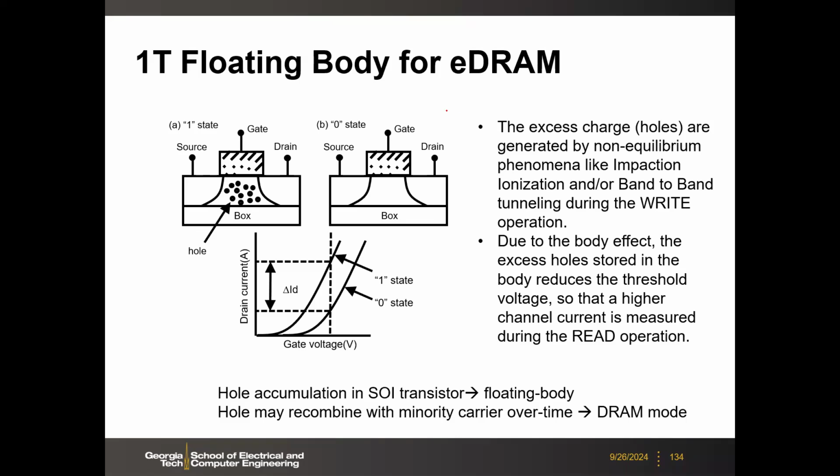Here, there's one idea called the floating body EDRAM based on a single transistor. Basically, this is capacitorless. You get rid of the capacitor. There are many ideas to do DRAM without a capacitor, which we call capacitorless EDRAM. One idea is this floating body. This is typically based on an SOI wafer, so you have the buried oxide, and then you have the floating body.